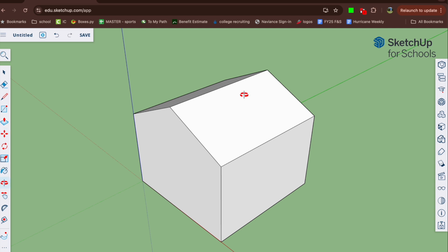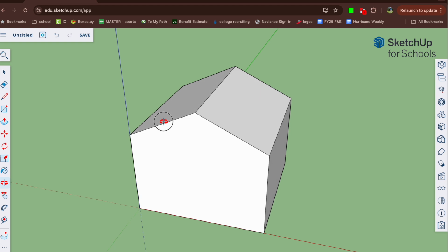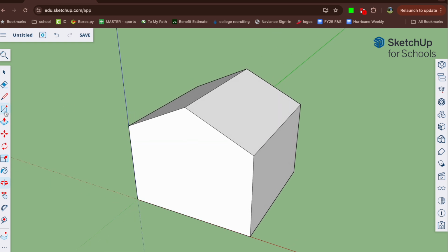I'm going to go back, hit the orbit O key, scroll around. And now we're going to grab the rectangle tool one more time. And I'm going to go on edge. I'm not going to do midpoint. I'm just going to approximate. We're not doing any measurements. We'll get to measurements later on. I'm going to click once, release, and then make whatever size door you'd like.